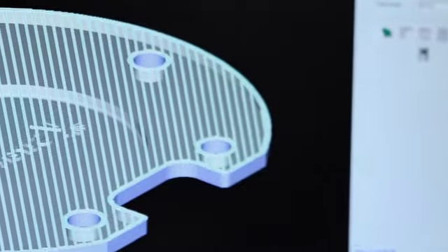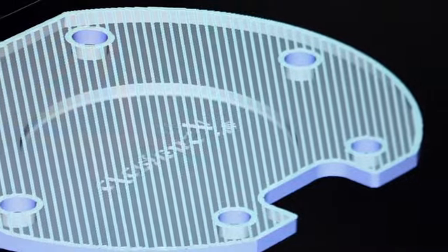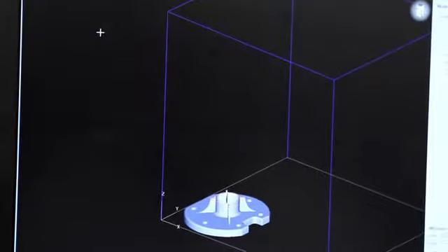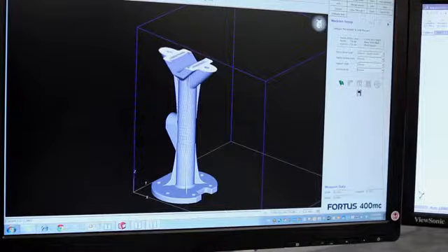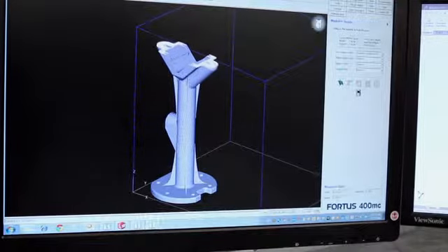On the other hand, decreasing the density of internal structures creates lightweight tools that enable more of the robot's payload to be utilized for heavier work pieces. Region by region, the fill density can be adjusted to custom tailor the tool's performance by creating gradient densities throughout.